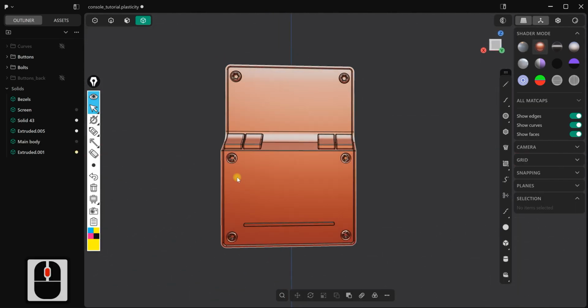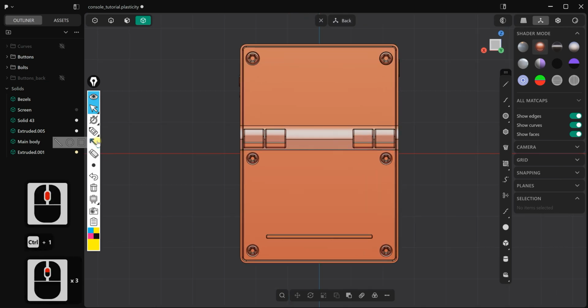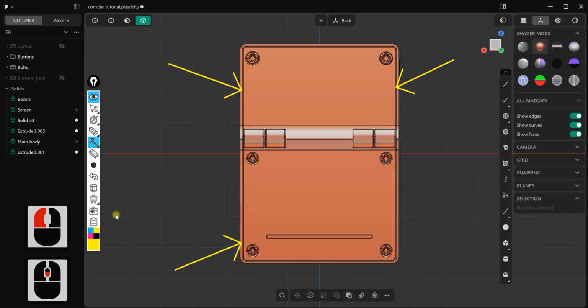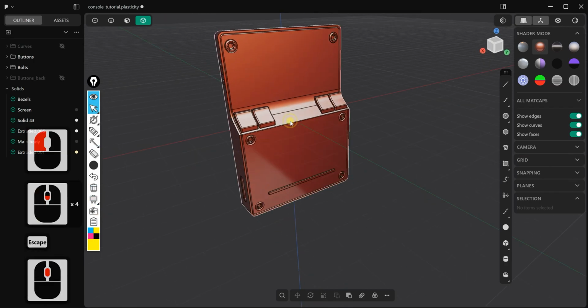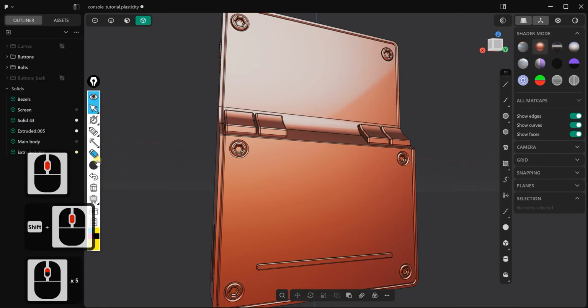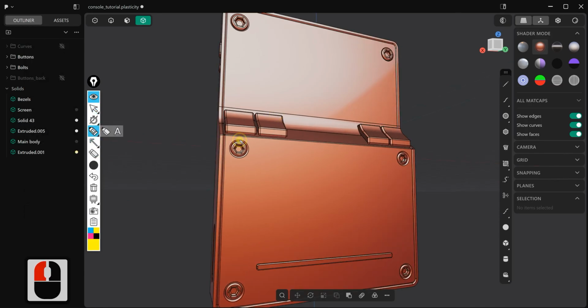I just noticed and already finished the modeling, but we're almost done. I'll try to explain what we need to do. We cut this mesh to make our back panel. We added fillets. Make sure you select only back edges. Then you simply unionize the front and back parts with the QQ command. The next thing, we use a circle, duplicated it and moved up and imprinted it.